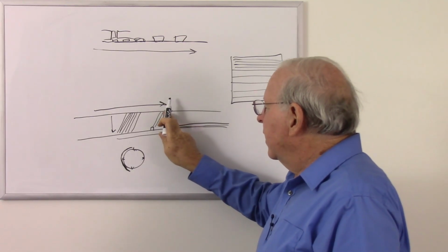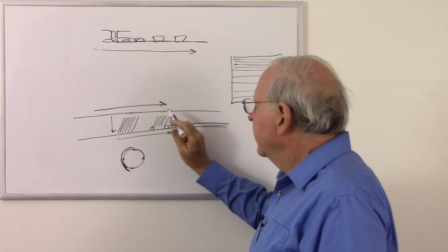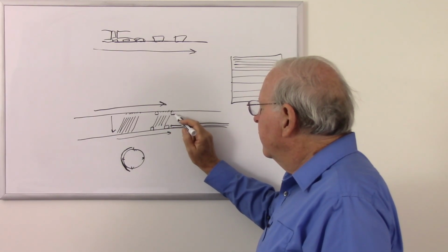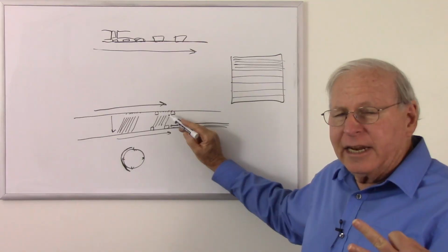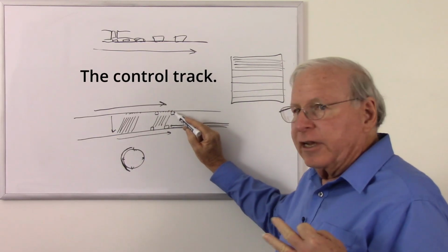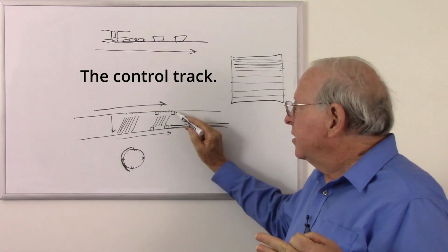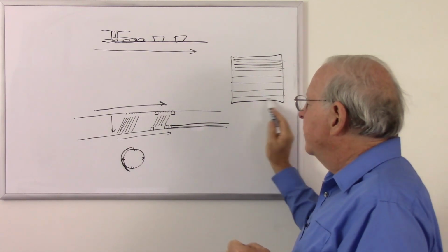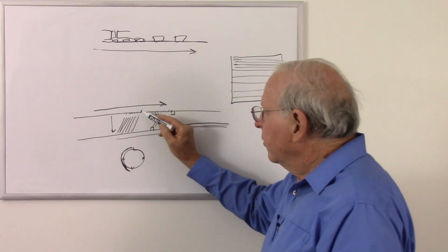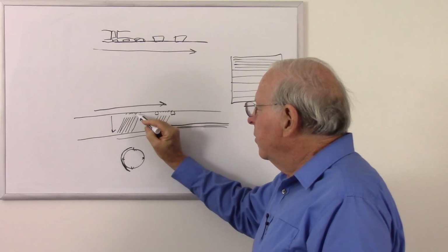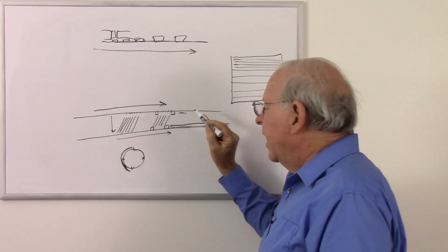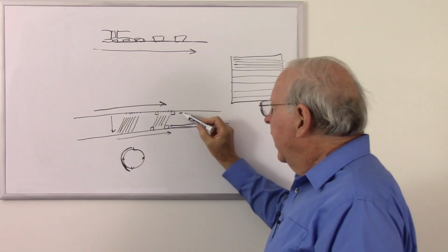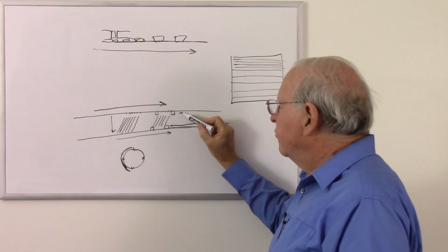We also did the same thing on the other side of the tape. Once again, we'll put the erase head here. And this one wrote in tracking information and digital information, at least in later ones, that could tell you where you were on the tape. So each time it scanned a whole frame of video, which would be several of these lines, it would put a code on this track here saying what number frame that was. So it would number the frames and give you a number. And this was digital information once again.